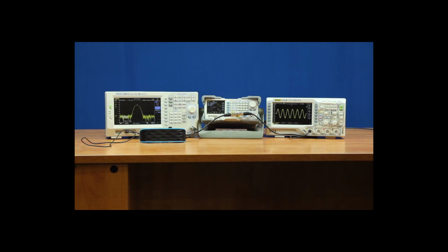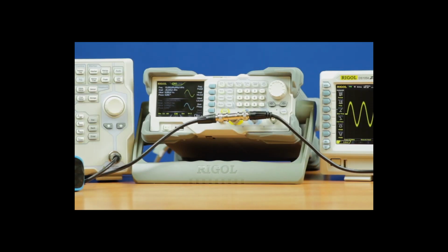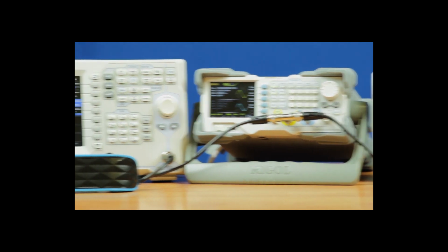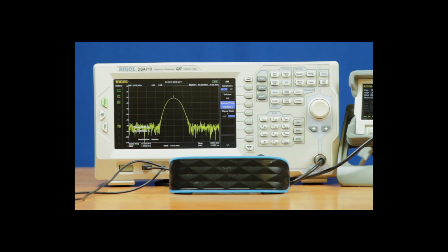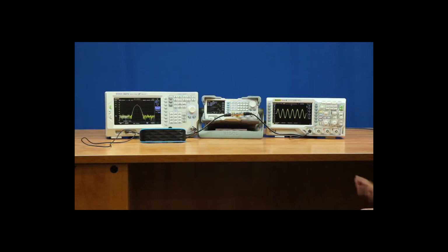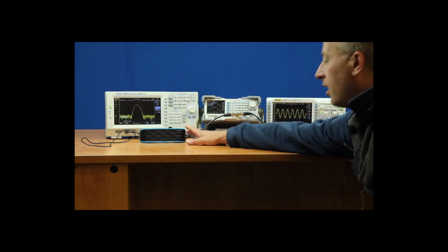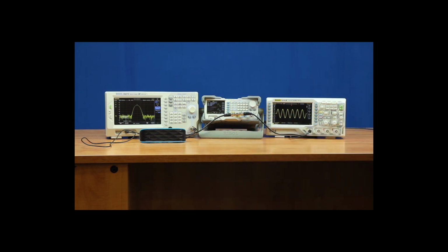So here we've adjusted the configuration only to add an external modulation source in the back of the DG1Z. There we're using my phone just to play a little classical music for us while we demodulate it. So here you can see the generator is modulating that signal, putting it up on the 10 megahertz carrier, and then transmitting it really in this case both to the scope and the spectrum analyzer so we can visualize it. Then the spectrum analyzer is doing the additional work of demodulating the signal into the speaker here where we can hear our music come across.